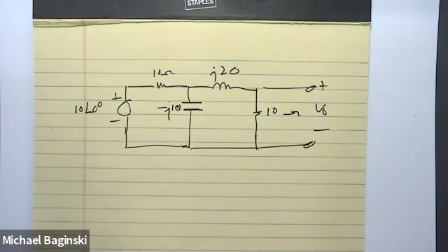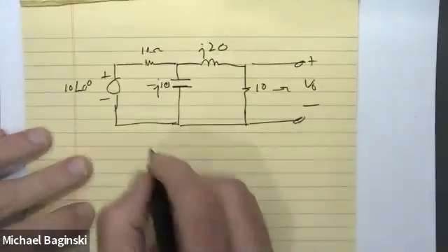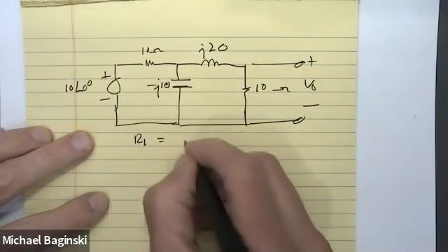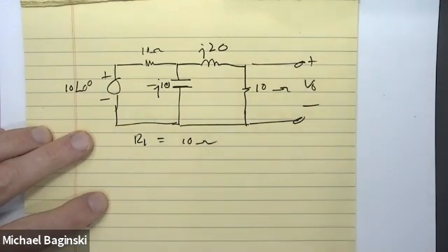But I want to use Thevenin's theorem. Can everybody hear me okay with this one? Now, there are several ways to do it. Besides Thevenin, nodal would work very quickly with this one, but I'm going to go ahead and use Thevenin's for this. So first, I have to identify the load. RL here is 10 ohms. Does everybody agree with that?